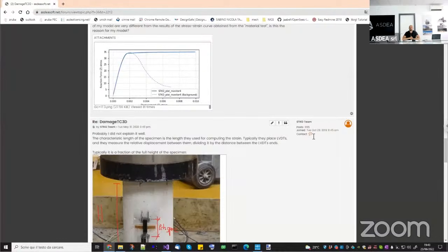About the next webinar for reinforced concrete shear walls, will fiber-based modeling be discussed? Yes, but what we will do is show shell models, solid models, the beam truss model, and also the multiple vertical line elements, the MVLEM element in OpenSees. That is actually a macro element that contains several fiber beam elements, so it's similar to the fiber beam approach in this sense.